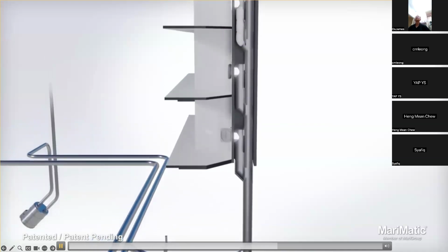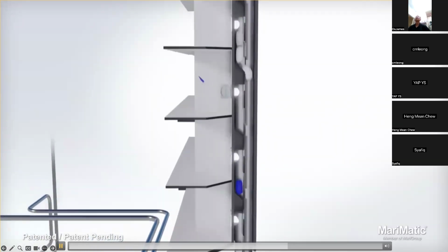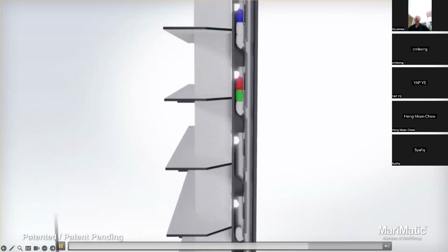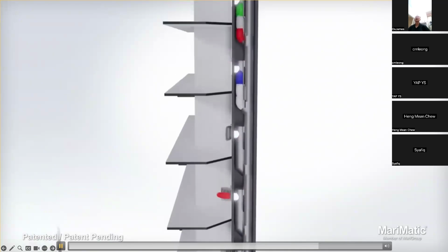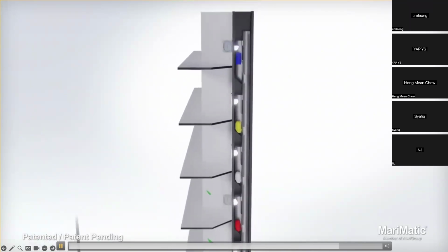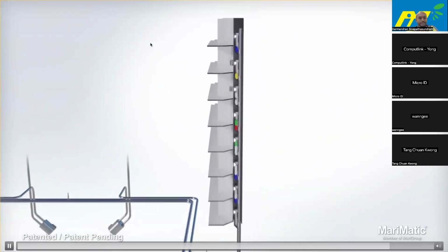Since there are more than 4 floors in a tall building, we use multi-door interlock to lock all the chute doors. You add multiple I/O boards that can communicate with each other to make it a multi-door locking system.